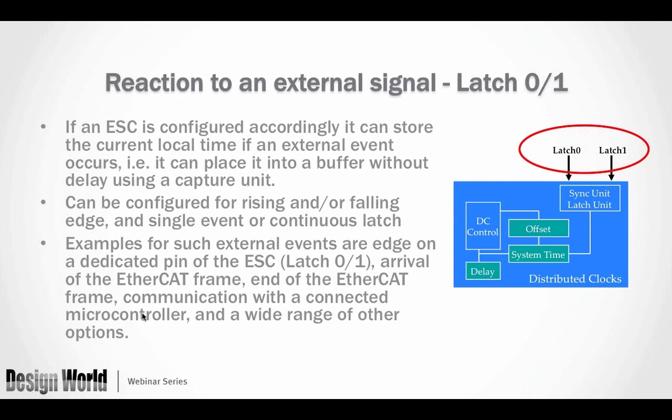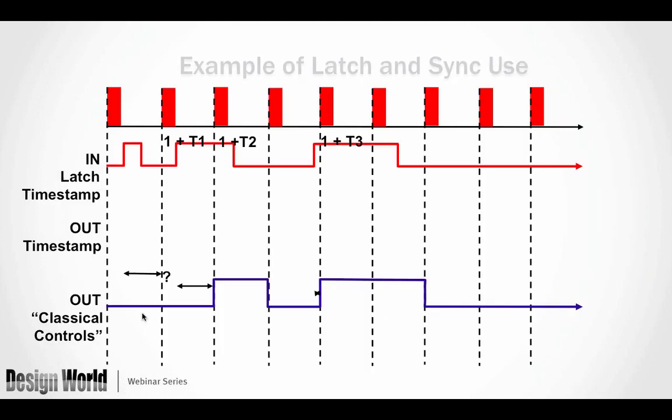So these can be implemented for a low-cost digital input module, which would take the place of a high-dollar device with a microcontroller embedded in it. Or you can also use this, as you've seen, for latching the time of EtherCAT frames, etc. So some pretty low-tech examples, but interesting examples of using the latch and sync.